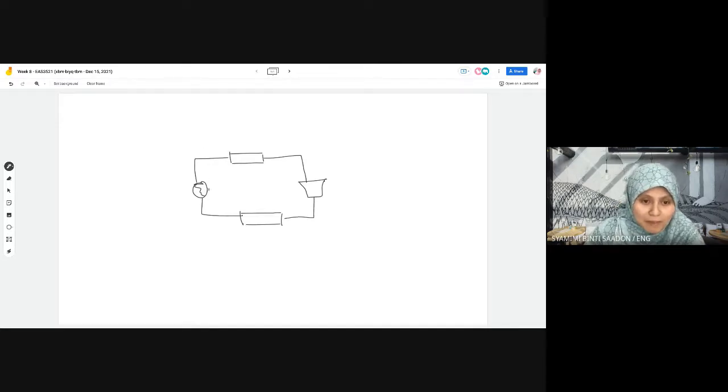So this is the pump or compressor. This is for a closed cycle. This is not an aircraft engine cycle yet. It is a closed power plant cycle. So we have an evaporator here, not a combustion chamber. A combustion chamber is usually for an open cycle or aircraft engine. For a power plant, using gas or liquid, here we have an evaporator or boiler.